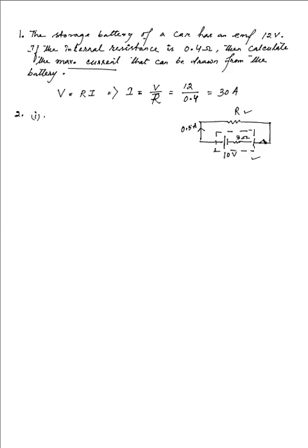So this is the first bit of the question, where you have to obtain the value of R, that is, the external resistance or the resistor connected to the circuit. This is a switch which is closed, such that the circuit is running. As you can see, R and 3 ohms are in series, so the total resistance is 3 plus R, and the total EMF in the circuit is 10 volts.